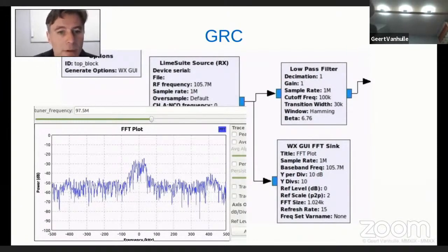The result here is the spectrum, and it's tuned exactly here to a radio station at 97.5. And what we see here, an FM radio station in the radio band is typically 200 kilohertz of bandwidth. And this 200 kilohertz of bandwidth is here presented as plus 100 kilohertz above the zero line and 100 kilohertz below the zero line. So our 0 hertz frequency line is actually the middle of our frequency of interest. You see, so we have a down conversion to 0. Our baseband is below and above 0 hertz.